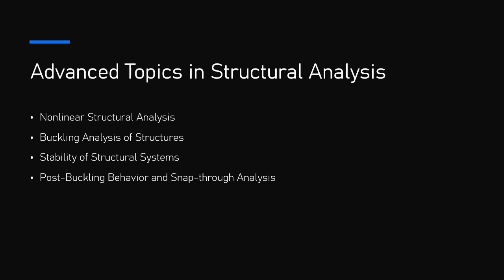2. Finite element method, FEM. The finite element method is widely used for complex buckling problems involving irregular shapes, varying material properties, and complex boundary conditions. FEM can model the structure's response under loading and determine the eigenvalue corresponding to the buckling load. Buckling analysis in FEM involves solving an eigenvalue problem where the critical buckling load corresponds to the first eigenvalue, and the buckling mode shapes represent the structure's deformation under the applied load.